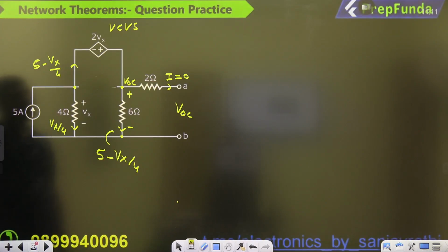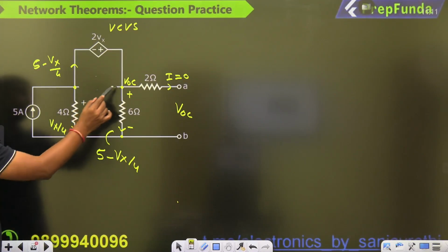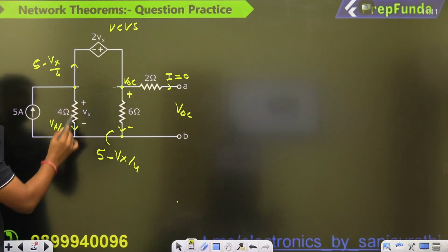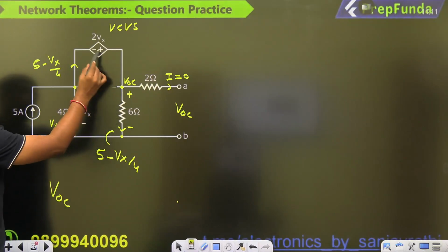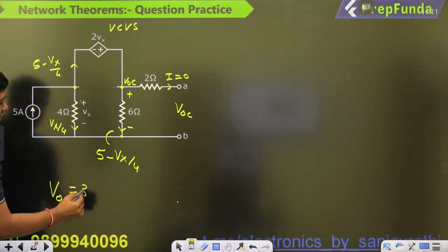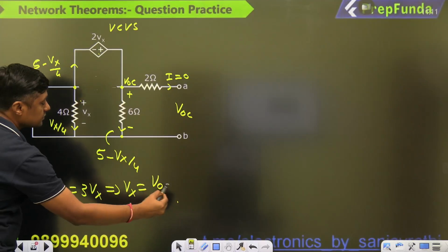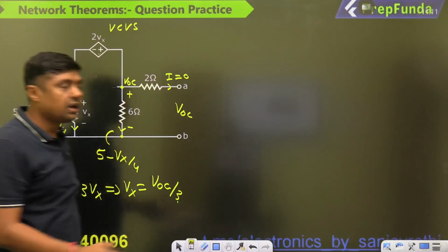Now, what is the relation between VOC and Vx? Very simple thing. Watch it carefully. What is the voltage at this point? VOC. From this point, what is the voltage? 2Vx. What is the voltage? Vx. So VOC is equal to 2Vx plus Vx. It will become 3Vx. So Vx is equal to VOC by 3.